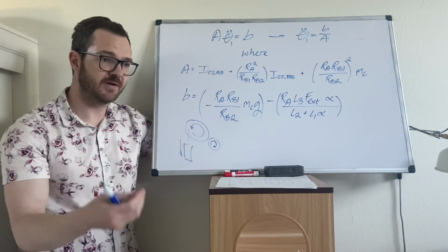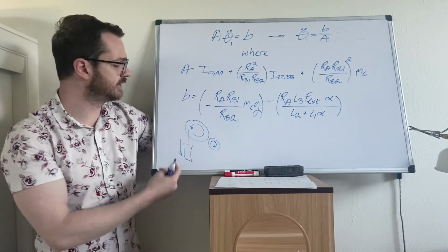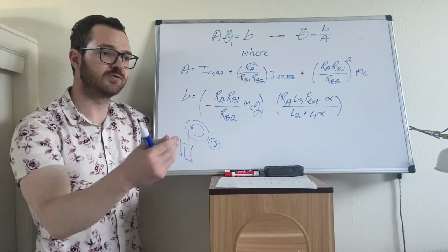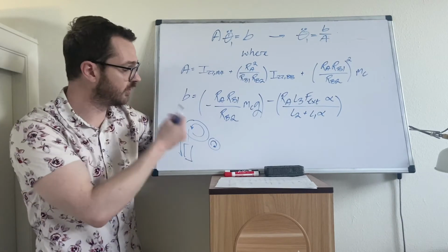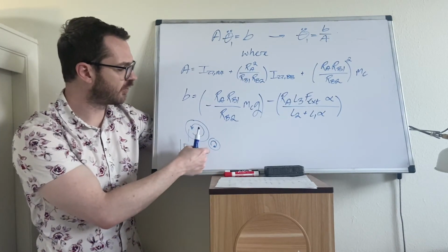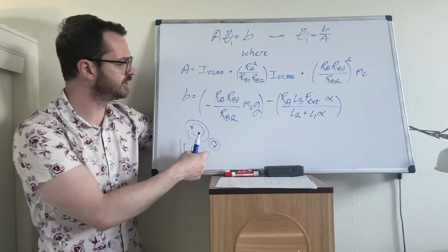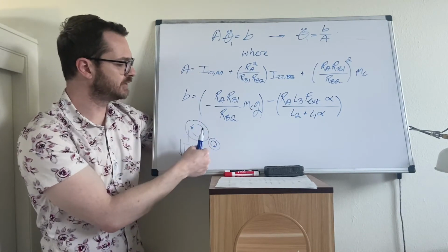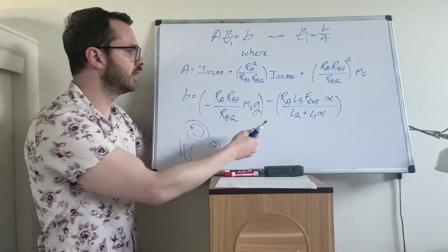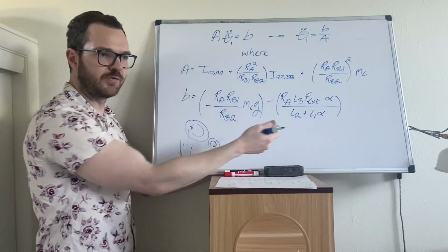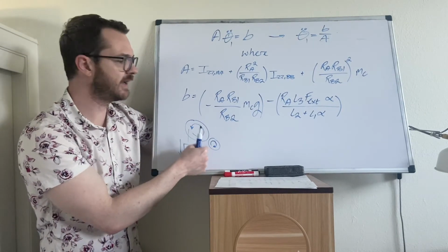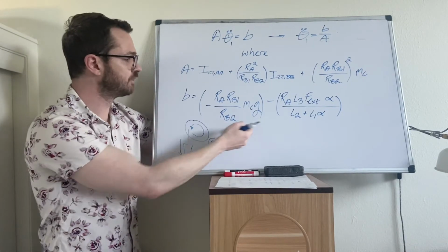That means that if your disk is rotating in a positive direction, the weight of the block is actually helping you stop your disk, your system. If disk A is already rotating in a negative direction, the weight of the block would make disk A accelerate. All else being equal, if there was no external force applied, the weight of block C would make disk A accelerate in a negative direction.